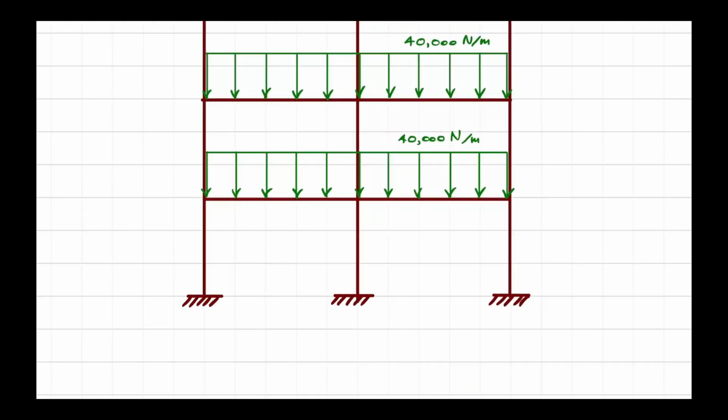Just a tip, I don't know if it should be called that, but you can see that when you analyze the structure, you will apply some boundary conditions there. When you apply the boundary condition, the structure in the real construction never comes back to you and asks, should I behave this way? It is your job to design everything such that it behaves like the condition you posed in your analysis. So for this case, if this is the model we have at the analysis phase, using the fixed support at the base like that, what will be the condition that you have to put in the design? Fixed support means it was restrained against all displacement.